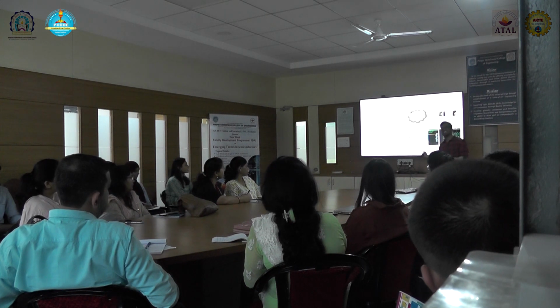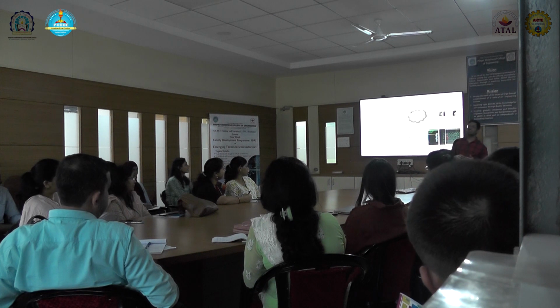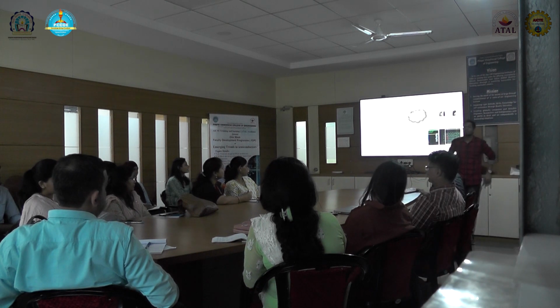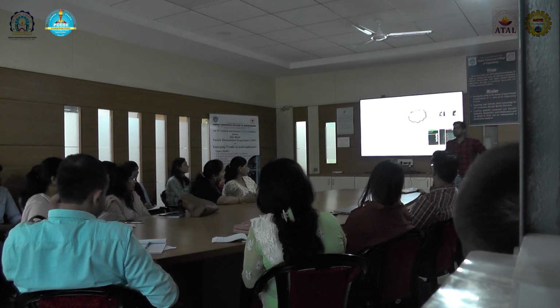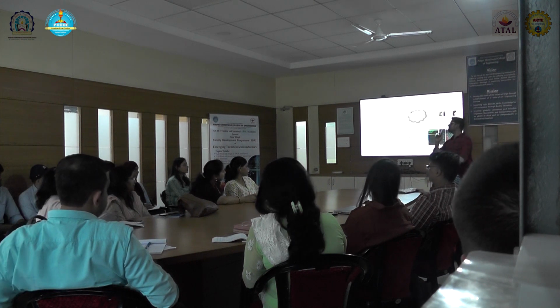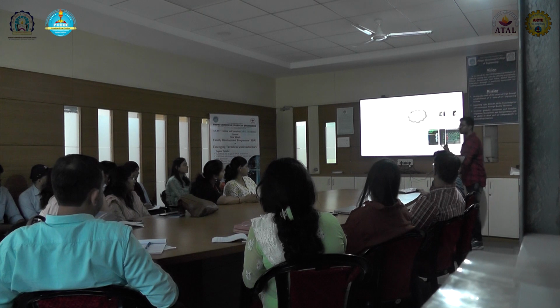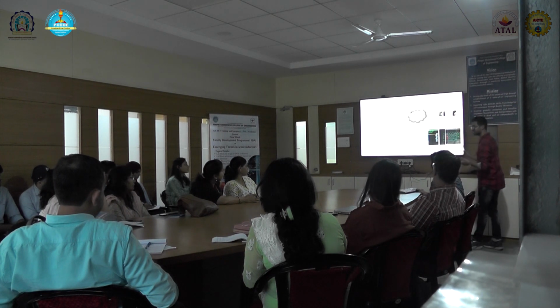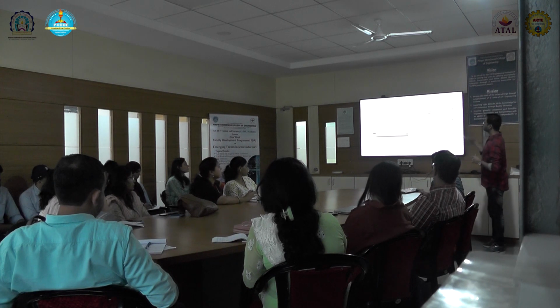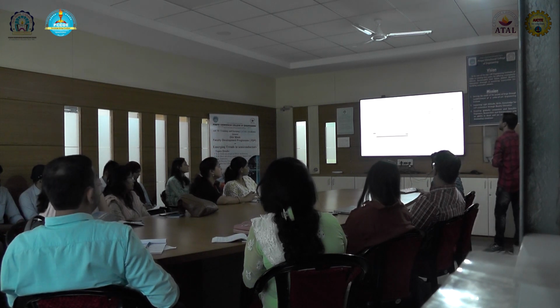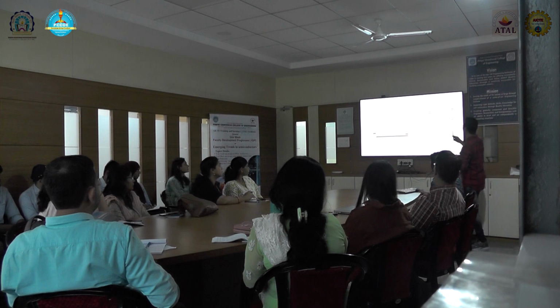Why do we write on output? To check the expected, correct. An assertion is something which should always be true, and output should therefore always be true. Therefore an assertion is written on output. So we will write a property for our DUT where we check the behavior of our output signals.